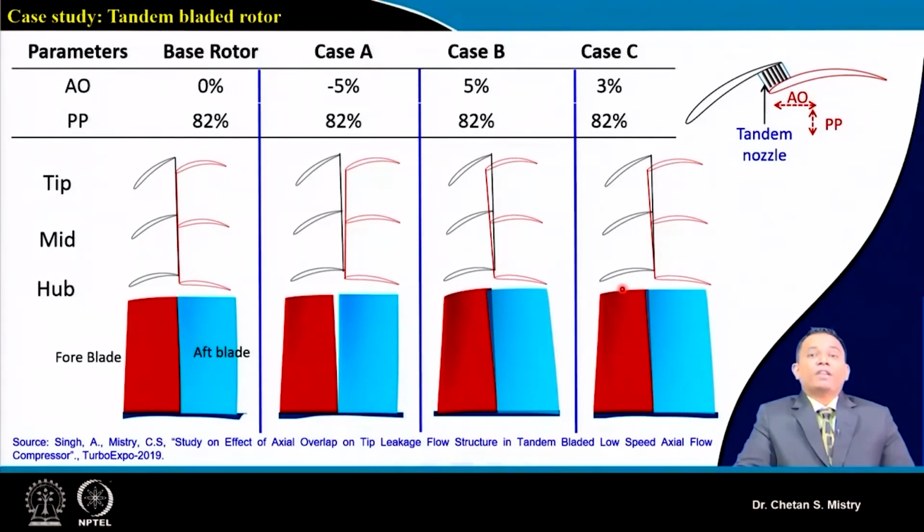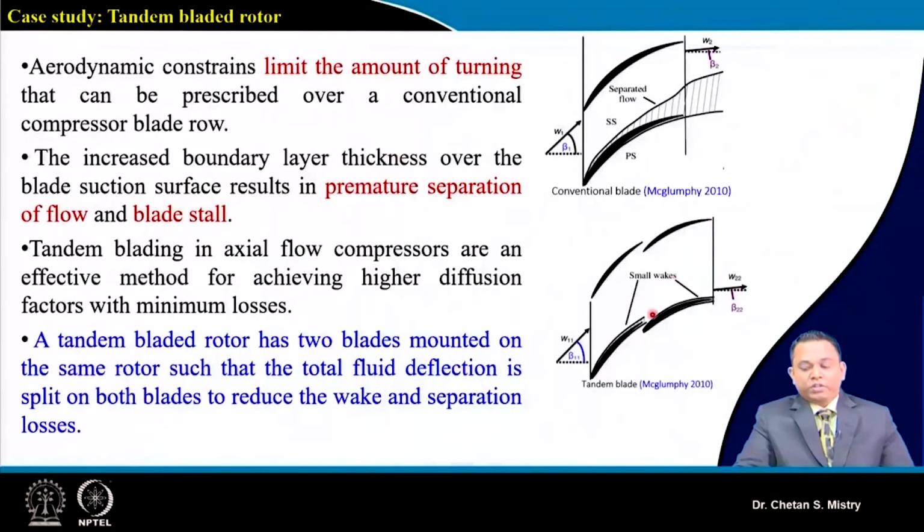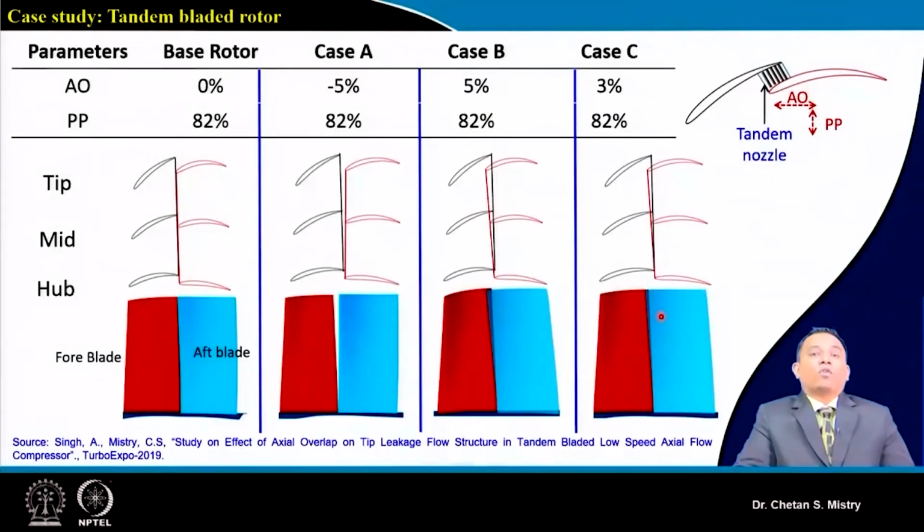We want to take the benefit of flow. So here this is the region, basically the trailing edge of my blade 1 and leading edge of my blade 2, that is acting like a nozzle, and that is helping us accelerate the flow on the suction surface of the next coming blade or blade 2. When we are doing this, this is giving the benefit. This work has been explored initially for wings, and later on people tried to explore it for rotor as well as for stator.